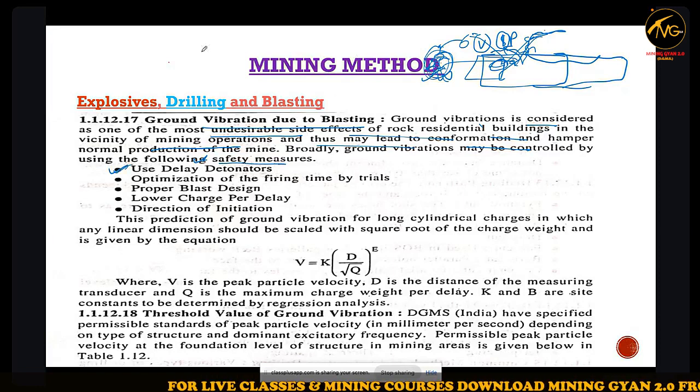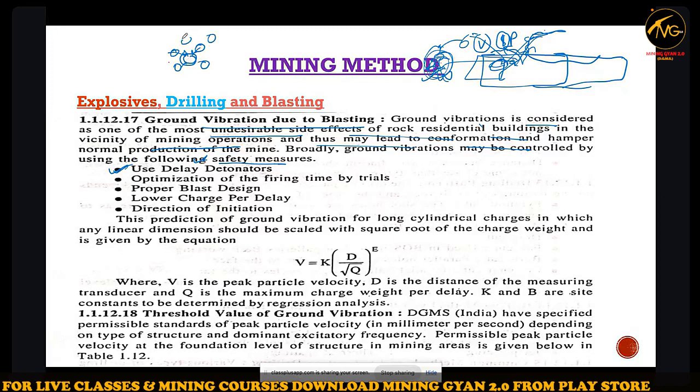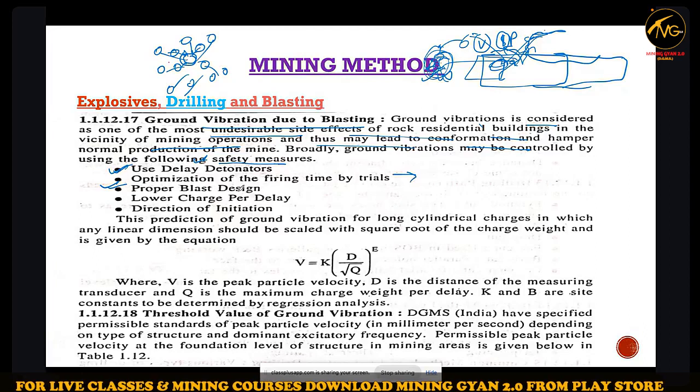Use delay detonators. We have studied the delay detonator: first drill a cut hole, then the delay element, this will blast, then the others blast. So use delay detonator optimization, and nowadays software is used to optimize the firing time.